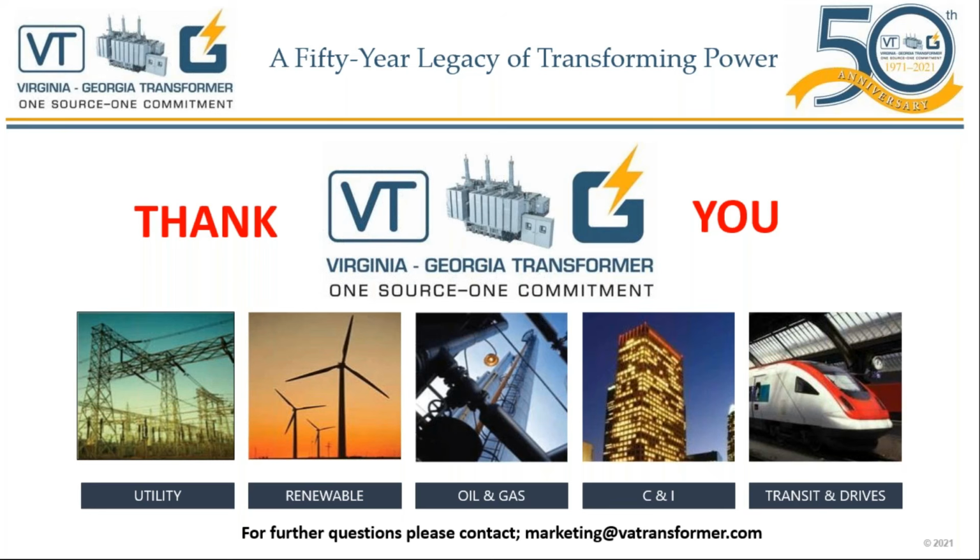However, there's also online DGA test equipment, which is connected to the transformer, has inlet and outlet, and continuously monitors the oil gases as the transformer is energized in the field. PD stands for partial discharge, so it's an electrical activity. Dissolved gas analysis is basically the result of electrical activity or heating or anything that shows up in your oil samples.